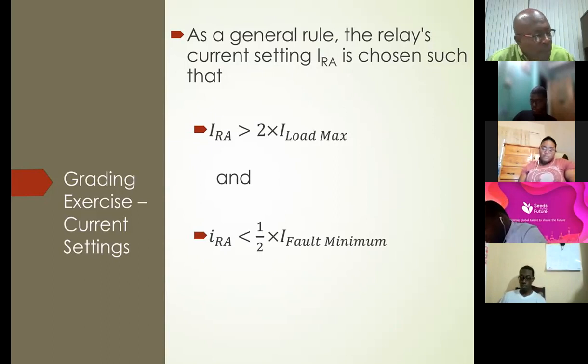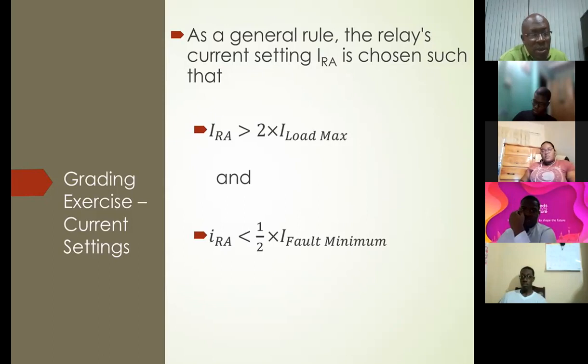Among them, during maintenance, depending on the bus bar arrangement that you have, you may need to shift load within the system. So you shift load from one transformer to the next while you're doing switching operations. Now, you wouldn't want the system to shut down simply because you have transferred load.